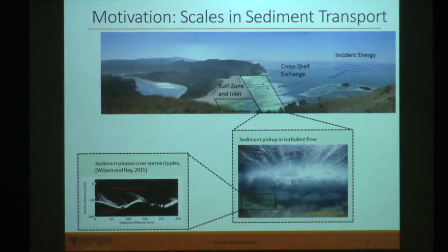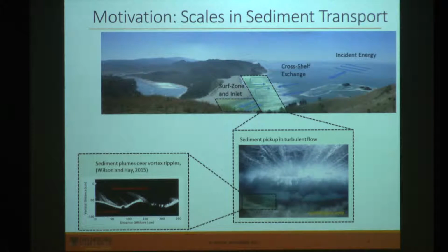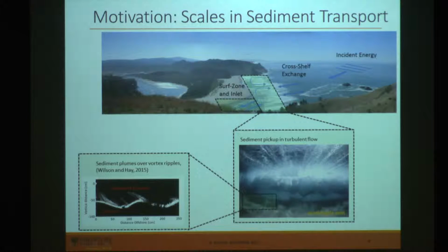And so I thought I'd start just with a bit of background motivation. As Joe said, I'm interested in nearshore processes and modeling in the nearshore. And one of the applications of nearshore models is to understand coastal change, so coastal erosion and accretion. But a big challenge to applying models in this area is the broad range of scales that are involved. And so we're looking at acoustic measurements at the smallest possible scale at the interface between the water and the sand. But most models don't resolve those scales, so the bigger picture of making these measurements is to try and develop new parameterizations for the larger scale models.